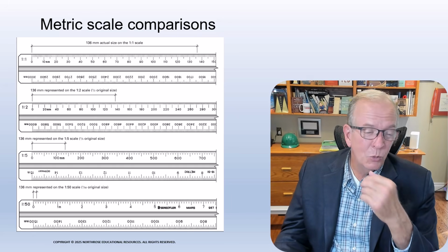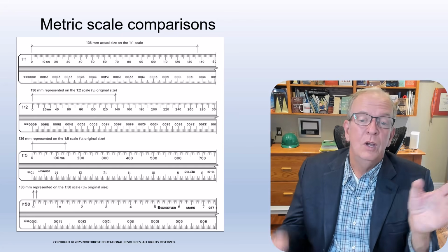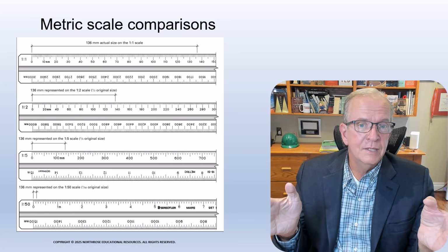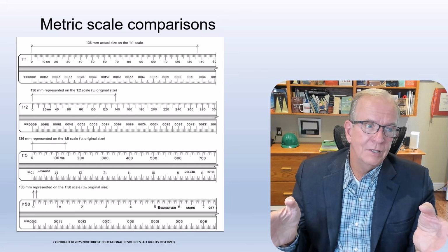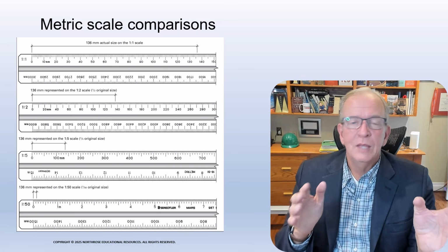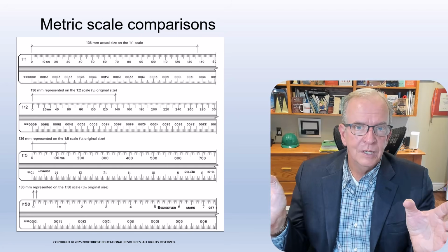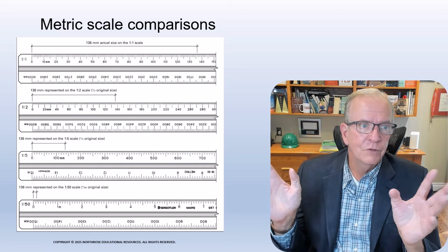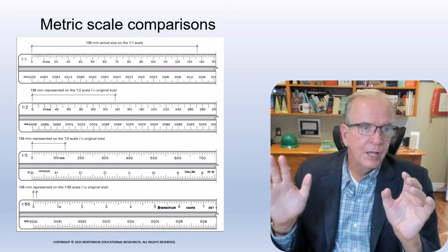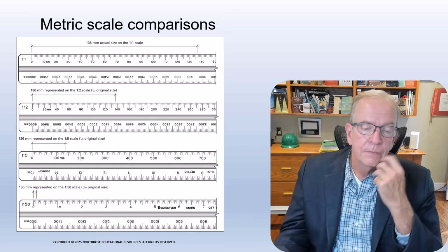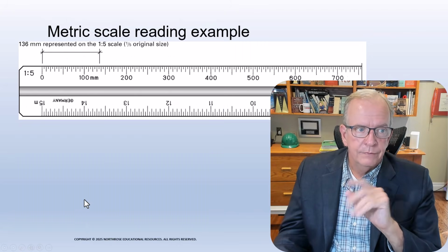But with that said, if I'm doing an estimate and I want to know, are these 16-foot 2x8s that I need, or are they 14-foot 2x8s? You should be able to tell, okay, no, I'm going to order the 16-footers, right? Because it looks like it's probably going to be about 15-foot 8. So I'm going to order 16-footers, right? So it's good for that stuff, definitely.